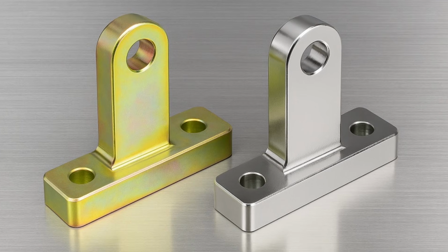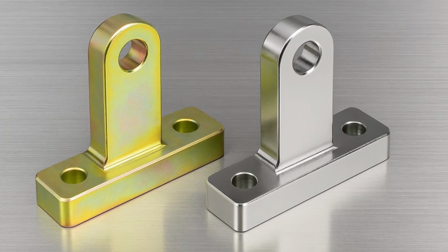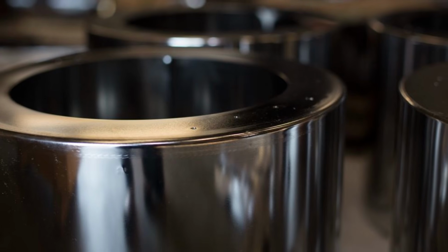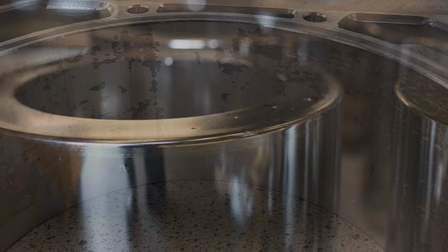Because if we choose carbon steel or any other steel, we must apply some surface treatment like plating or coating to resist corrosion. And these coatings have uneven thicknesses. They cannot be controlled accurately, and they may peel off with time. So for better dimensional accuracy and dimensional stability of the critical components, especially in tough environments, we prefer stainless steel.